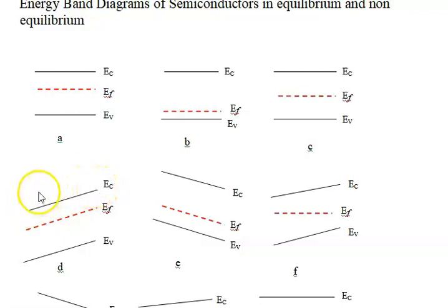The electric field, therefore, goes from left to right. A hole would be moving from left to right. An electron would be moving from right to left. In this particular case, there is a hole current, even though the material is doped N-type, just very slightly N-type. There is a drift current going from left to right in the positive direction because the electric field goes from left to right in the positive direction. The current is positive, holes move from left to right.